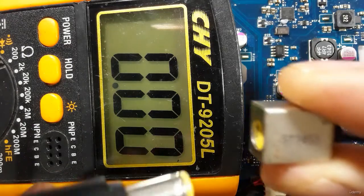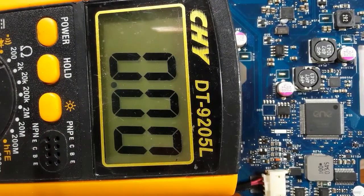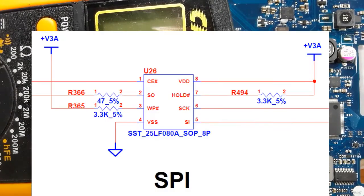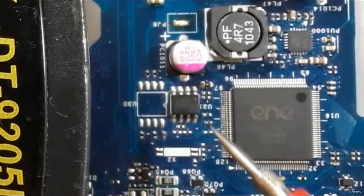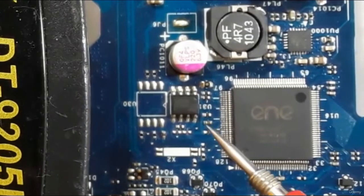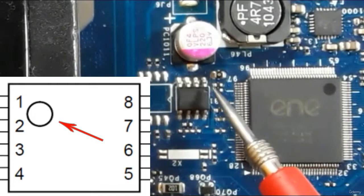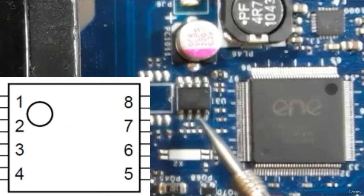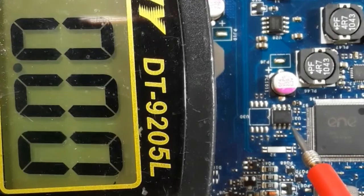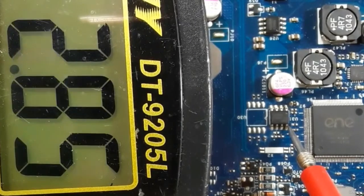So let's plug in the power adapter and then check pin number 8 of the BIOS. As you see in the schematic, you will always find 3.3 volts on pin number 8 of the BIOS without powering on the laptop. We have this dot here, which means this is pin number 1, 2, 3, 4, 5, 6, 7 and 8. So let's check pin number 8. As you can see on the multimeter, we have 3.3 volts.